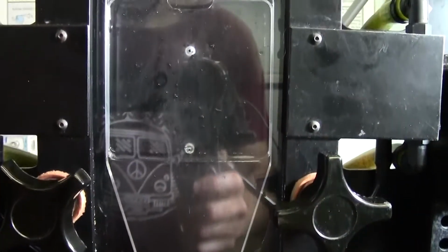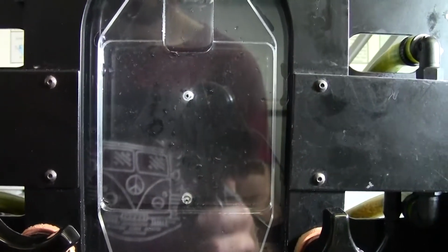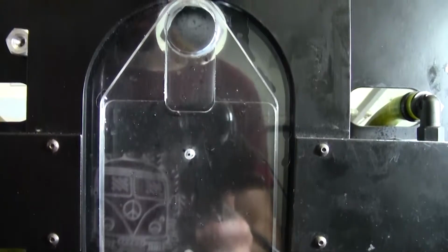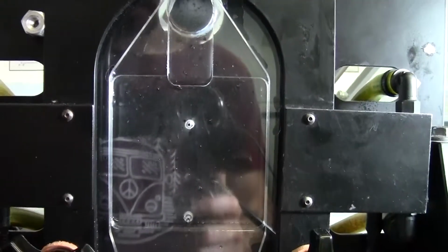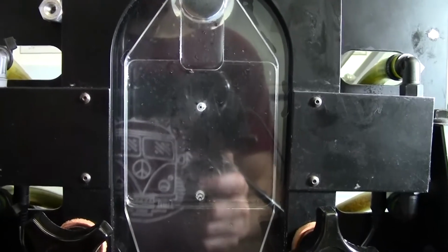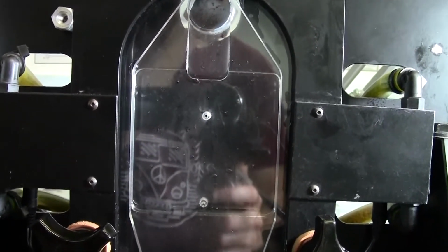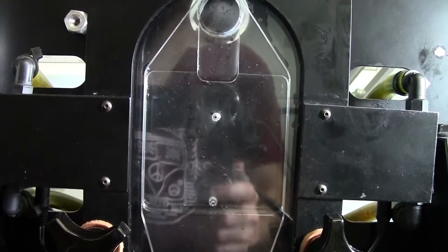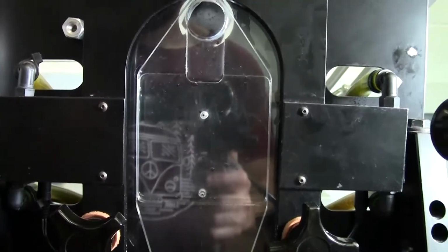Then the calm, uniform flow enters the main test section, flows through it, and returns to the water reservoir through the pipes in the back. Here in the test section, we have a controlled uniform flow, and we can put different geometries in front of it to see and study the flow as it passes these geometries.